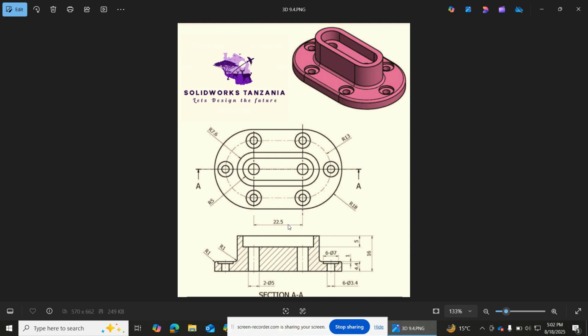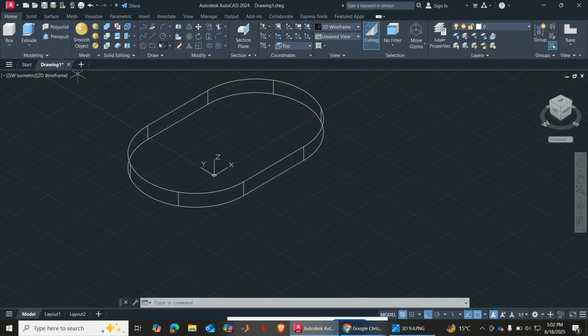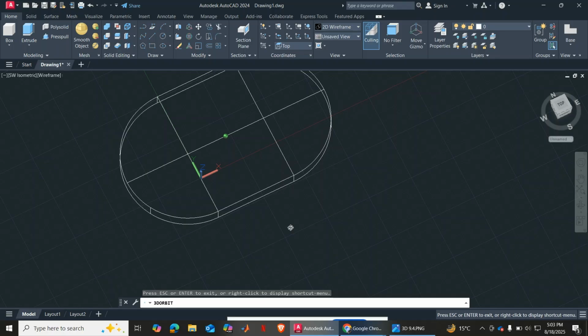We have 6 holes at those points where we have the center lines and the slot interfering. Okay, so let's do just that. So let me draw lines. Let's say a line from here to here, escape, another line from here to there, escape, another line from this center here to that center there, escape. All right, yeah.